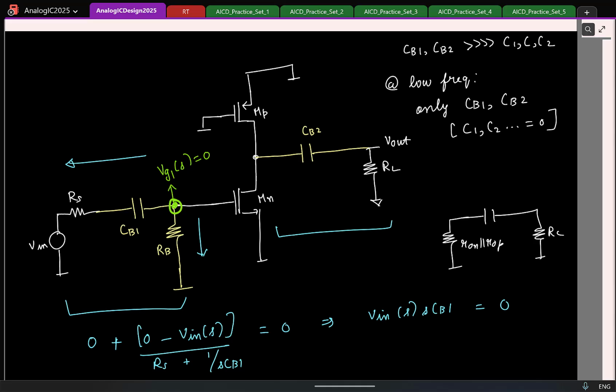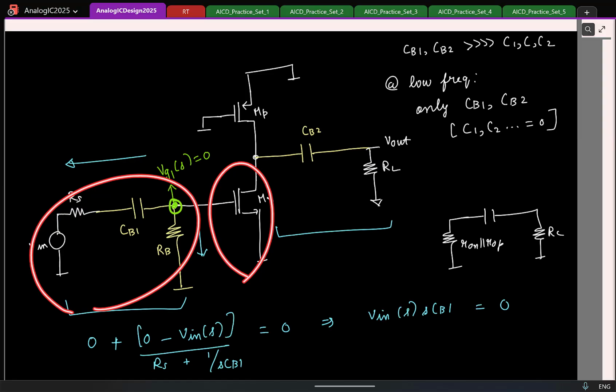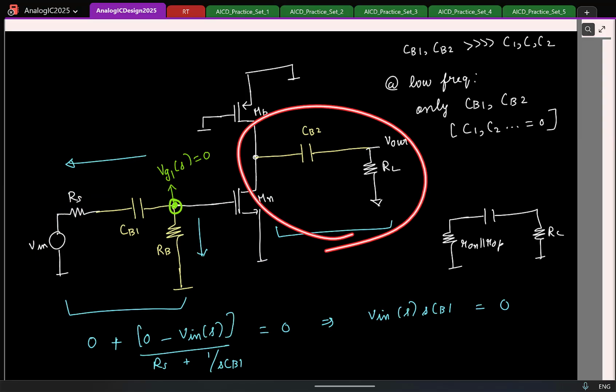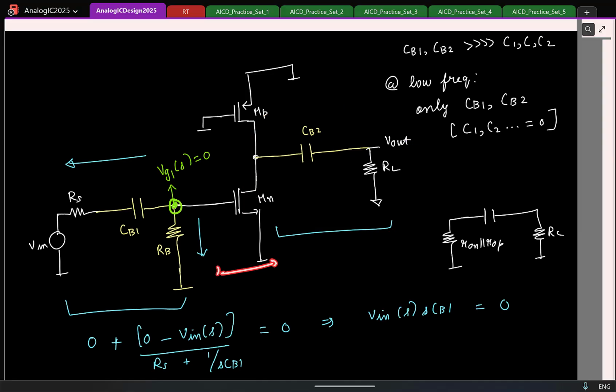Yeah, the idea is, I can think of it as 3 isolated transfer functions now. This is one RC section and this is one RC section. In between I have the transistor, correct? So if I have 2 zeros, I am basically saying that there is a 0 in this RC section, and a 0 in this RC section. Because they are uncoupled, I can treat them separately and find the 0 here and 0 here, that's all.